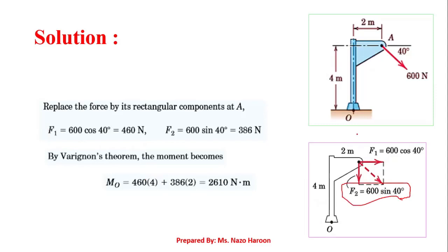If I draw the line of action of the force, it could be something like this, the vertical dashed line, and the moment has to be found about this point O. So the distance from this point O to the line of action that passes through the point of application of the force, something like this, has to be the moment arm distance, which is basically an orthogonal distance, at 90 degrees.